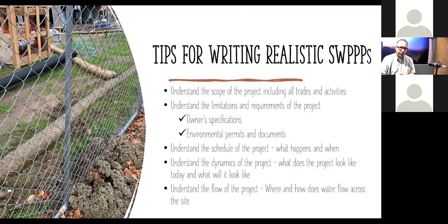Well, we might look for not only the type of BMP or things that are prohibited, but there might be certain bid items that they were only allowed to use. So I might want to look at the bid items for what type of sediment controls are allowed. Perhaps compost socks are allowed, but fiber rolls not, or vice versa. Perhaps silt fence is a bid item, but compost socks not. Perhaps gravel bag is a bid item, but compost socks not.